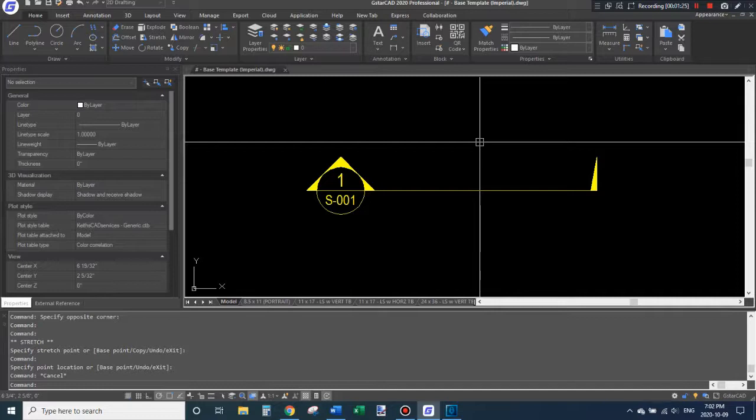The cons? Since I'm relatively new to GstarCAD, I'm sure I'll find more issues. So far, things have gone pretty smoothly. The only issue I've found is that when you edit a dynamic block's parameters, you'll get some unexpected results. For example, a flip state might switch on you. Compared to AutoCAD, you can expect more unexpected behavior when editing blocks in GstarCAD. This issue can be quite easily worked around if you only edit blocks at the start of a project and do a save block as. Should you absolutely need to change a block during a project, you should be okay.